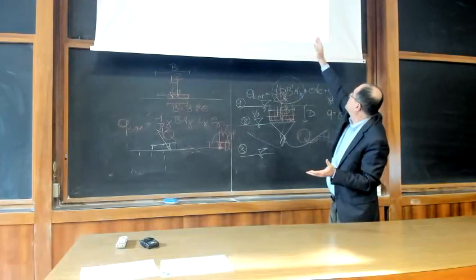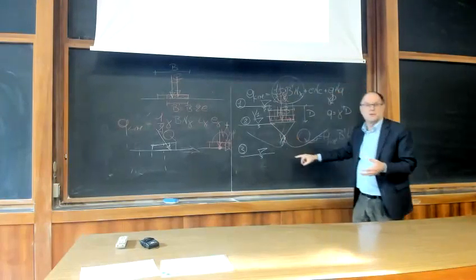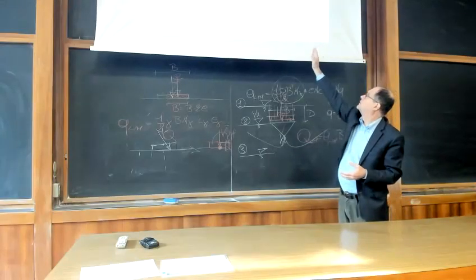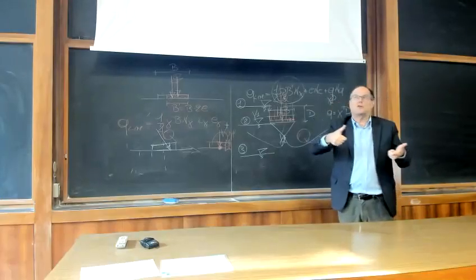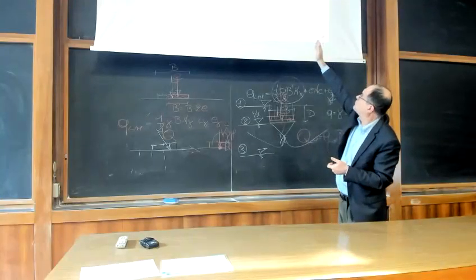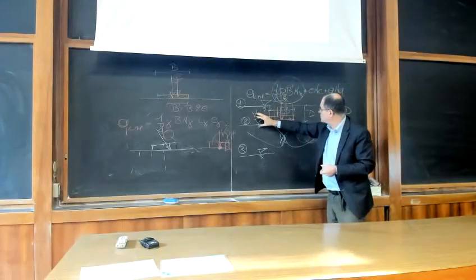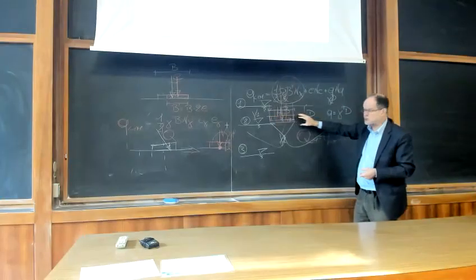So, for example, the plunging mechanism is the bearing capacity that we have discussed so far. If the vertical component is not affected by the combination of a horizontal load, you have a vertical straight line. The other possible mechanism is when the horizontal load is prevalent and this footing will tend to slide.